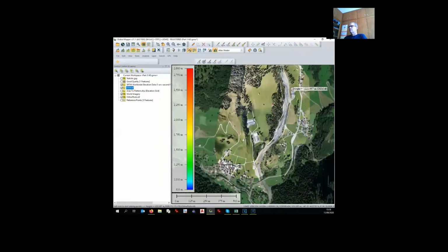It is important that our digital elevation model lies a little bit higher than the SRTM model. This is because if you do the water shedding analysis, the water will have to run into your system and not outside of your system, if you want to see if your site is going to be flood prone or not.